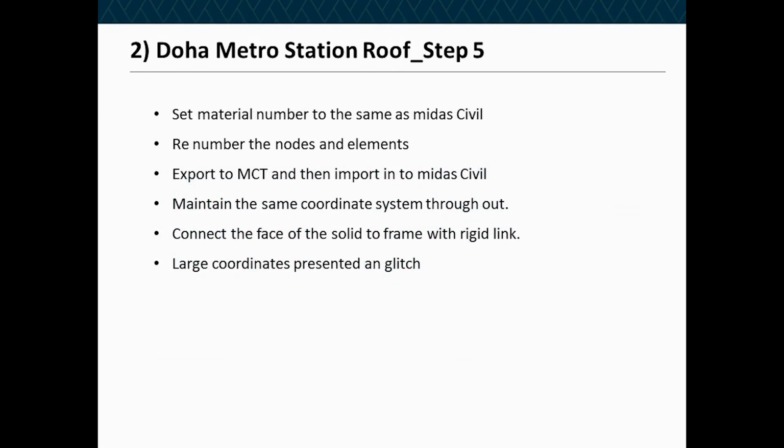Okay, so when you're transferring it back, you just need to be careful that your MCT file is compatible. MCT, for those that don't know, is MIDAS's command shell, they call it. It basically allows you to take syntax data from one model and import it into another.